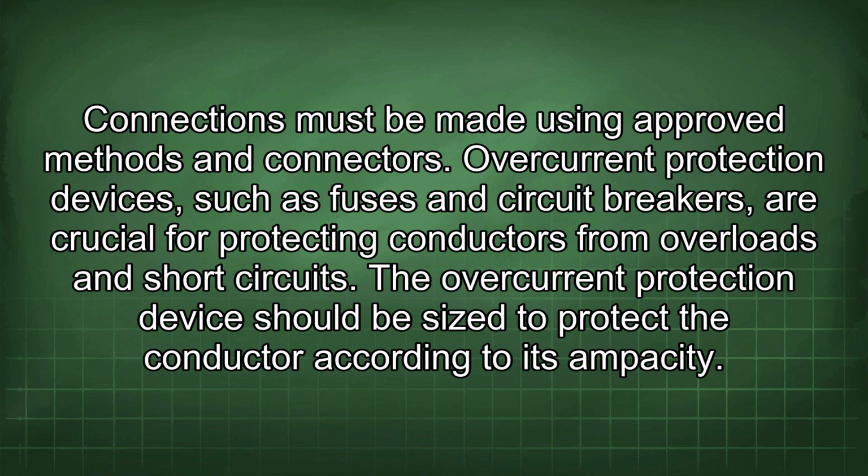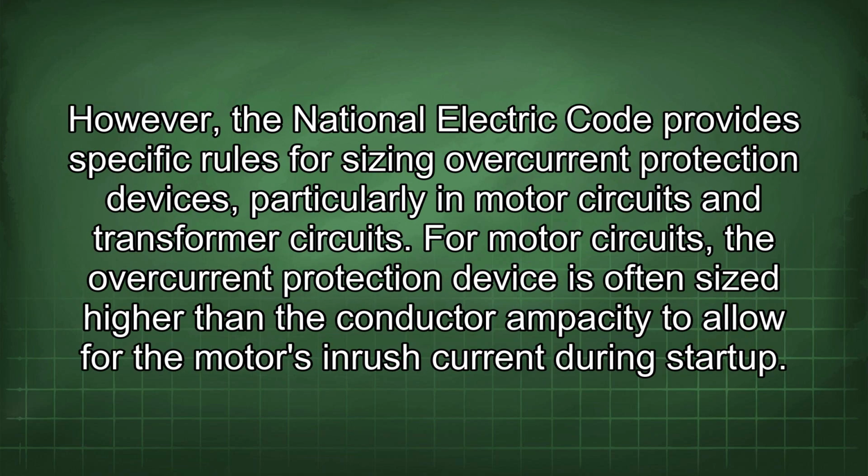Overcurrent protection devices, such as fuses and circuit breakers, are crucial for protecting conductors from overloads and short circuits. The overcurrent protection device should be sized to protect the conductor according to its ampacity. However, the National Electric Code provides specific rules for sizing overcurrent protection devices, particularly in motor circuits and transformer circuits.